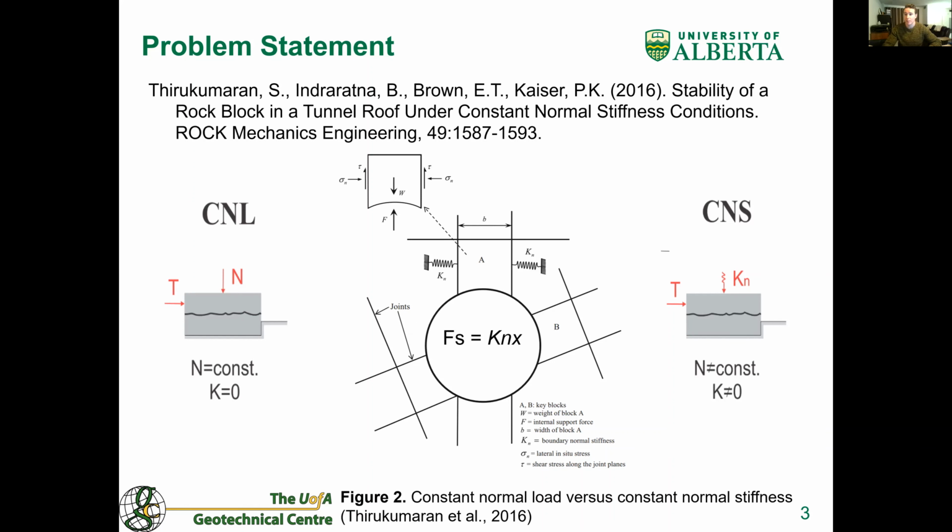Around underground excavations or along the shear zone of very large landslides, however, the far-field ground tends to act as a spring at the location where strain is developing, creating a constant normal stiffness condition. This boundary condition causes the dilative contractive response of the strained soil to behave according to Hooke's law, where the spring stiffness is equivalent to the rock mass stiffness. Restriction of dilation then creates the potential for shear-induced pore pressures to develop.